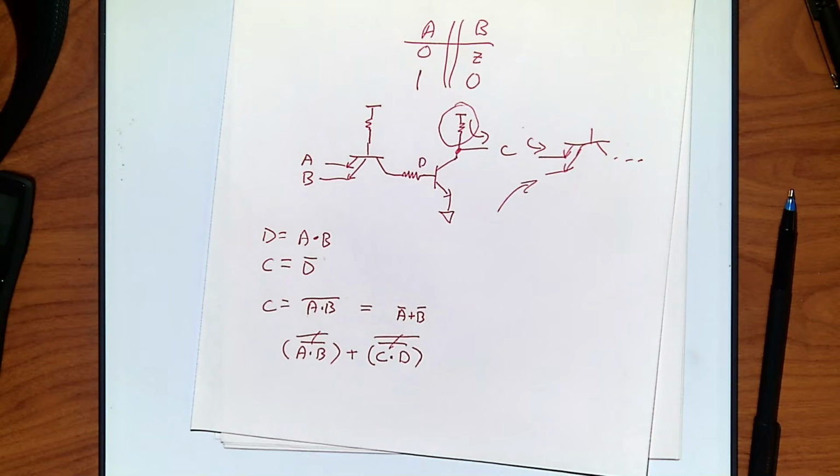But on the next side, I've got something that's not supplying any power, and I can control that power elsewhere. On top of it, I could take two of these gates and wire them together. Since neither one provides power, I can't get a short accidentally. This is what's called wired logic. If you have a Z output, you can hook multiple gates together to build an effectively larger gate.